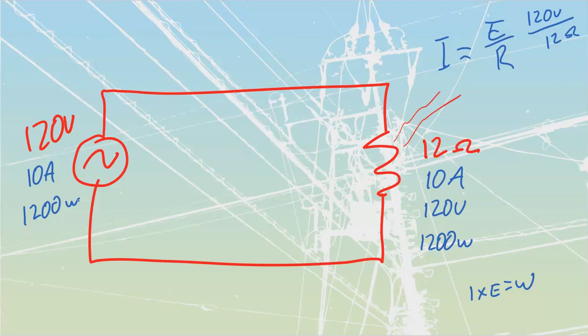The circuit balances. We see all of our volts that we have on the input side are being dropped across our load side over here. We see we've got the same current, 10 amps through the source, 10 amps through my load over here. Let's just draw out, at the very end here, what my power and voltage and current waveforms look like. So I'm going to draw out a voltage waveform. We'll make the voltage waveform this red one.